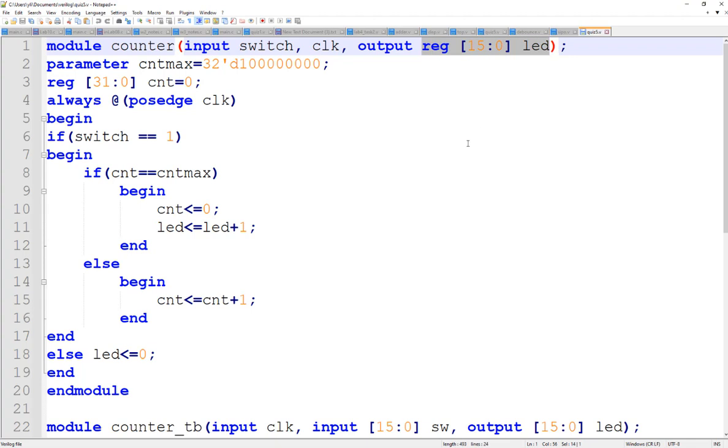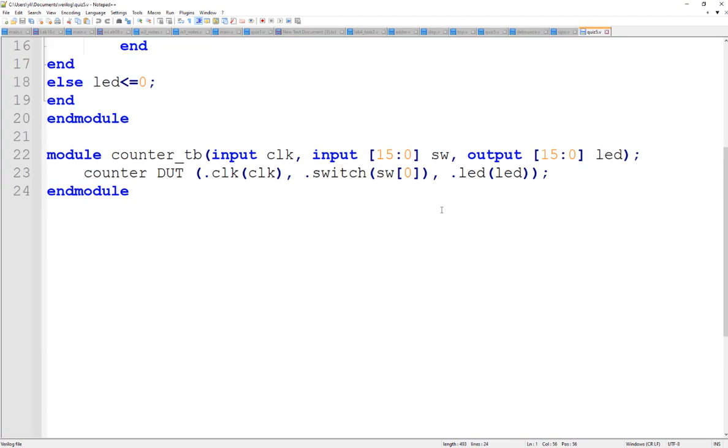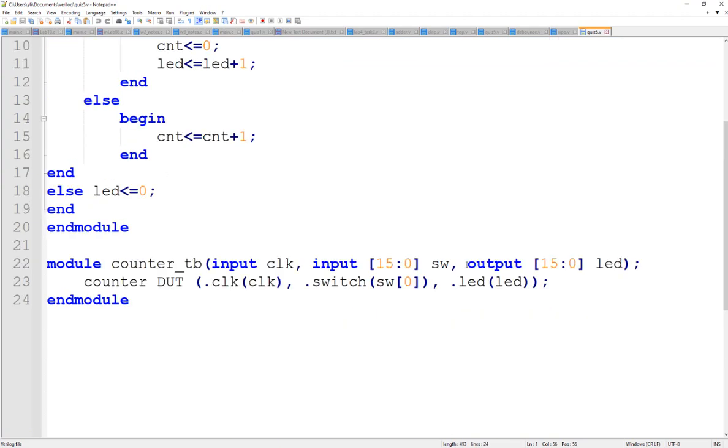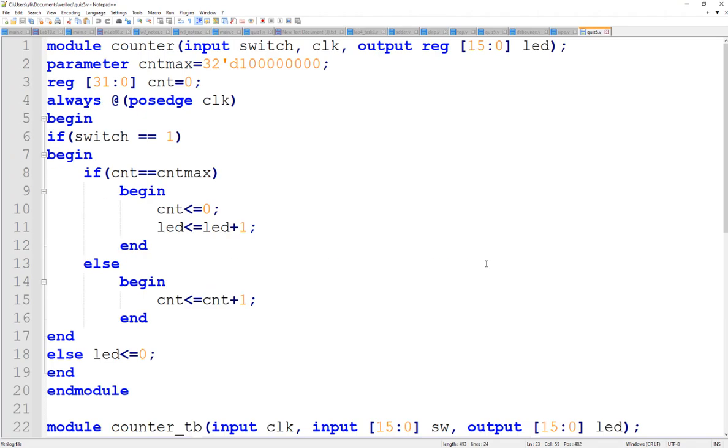You can find out that a lot of times we hope the output can hold the value for a certain period of time, can latch it. So we usually give that variable a reg type, since we know that eventually this signal will be shorted to this signal line, which we don't declare anything for, but is usually just a direct connection, could be a wire type of the FPGA. So we buffer that signal right before the FPGA output, so it's able to latch it.